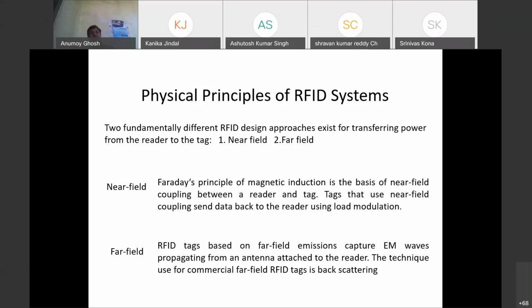The same thing is for tag antennas or reader antennas. An antenna is basically radiating some power in the wireless domain. So whenever it radiates power in the wireless domain, the power has two parts: one is the active part, another is the reactive part. Now, from the antenna, if we move away, there will be a margin, suppose x meter margin.